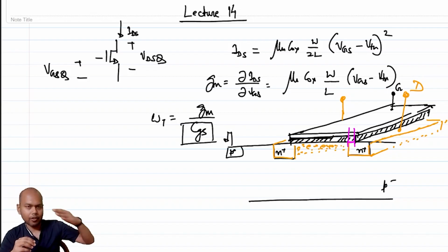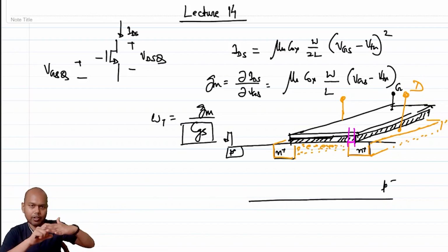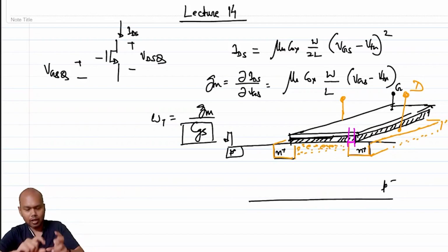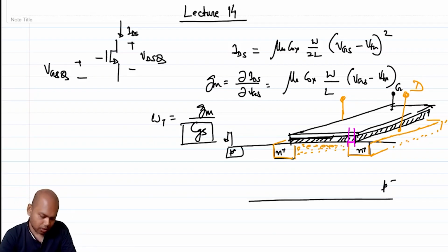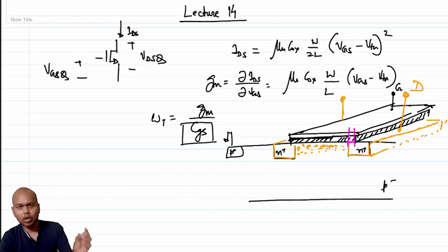So basically you have conducting material, an insulator, and another conducting material, which means it's a parallel plate capacitor, but the plate width is only that overlap part. So you are going to get a capacitance because of that overlap. What will be the value of the capacitor?